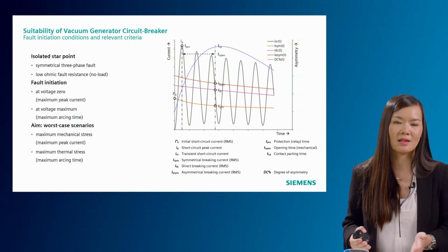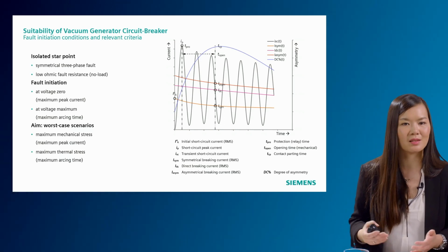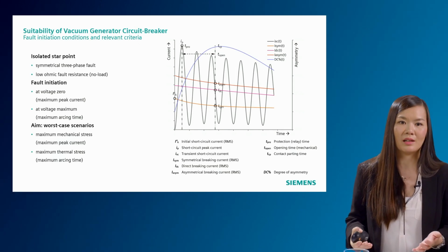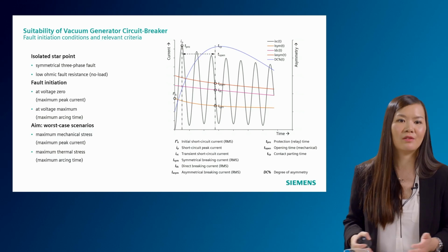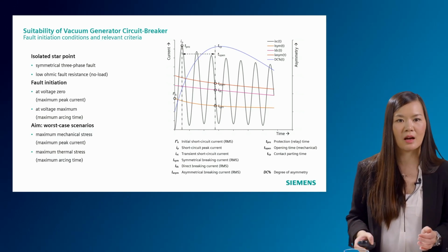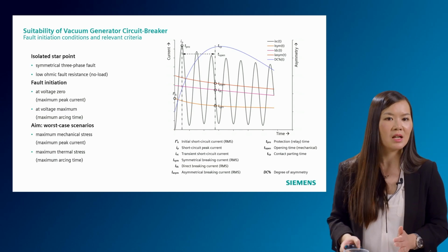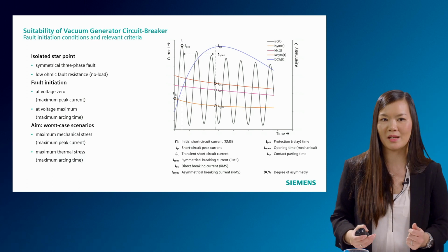In a real case, it depends on where the short circuit location will happen, whether this is in oil or in air, and what the distances of the bushing are. You can define a different level of arc fault for your case. However, we try to stick to the standard to simulate the worst case, so we use the 300 volts as recommended.